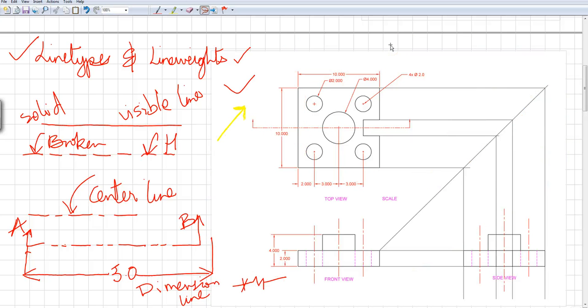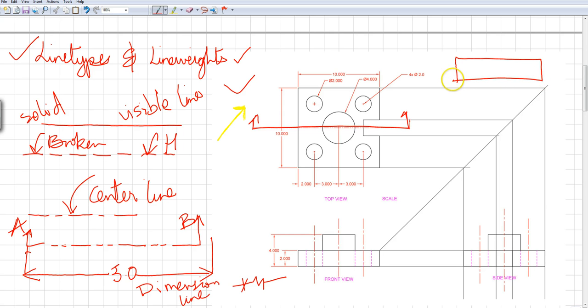So we already know what the section line is, right? This is our section line. Now if I were to draw what got cut out, maybe I need to draw it in a different place. I'm just going to draw over here right now. So that's the block that I cut out, and there's the cylinder, the top one that got cut out. So I'm going to hatch it.